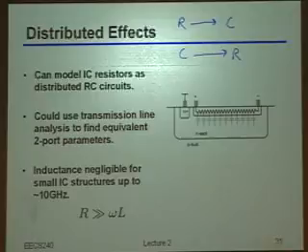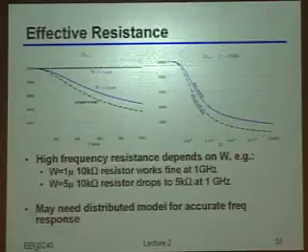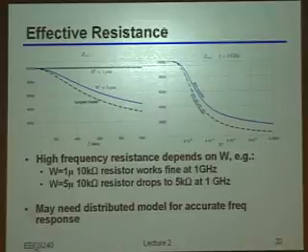We won't spend a ton of time on that. You could even get not just parasitic resistance, but some parasitic inductance. But the good news is, for most of the dimensions and frequencies we're talking about, that inductance is small enough that it wouldn't have a big effect on the overall impedance. But resistance inside of the cap, or vice versa, capacitance with a resistance, definitely can be a big deal.